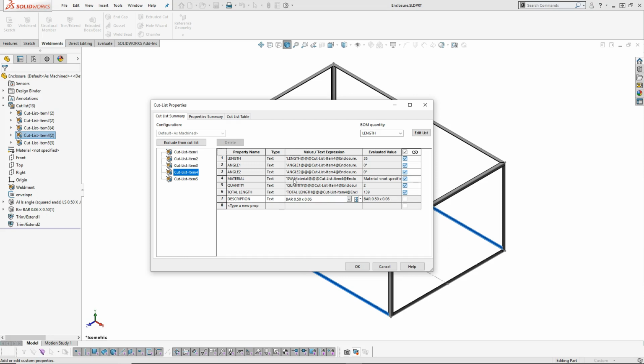Alright, and then the materials, if we needed it, all of it's going to be aluminum, so that'll show up somewhere. Either as the material that we haven't set yet. I was going to say that we set over here, but not quite. Alright, and then one more. So if we had a lot of these elements, the last thing I really want to do is go through and have to do that for each item. So tab, go back to the first.